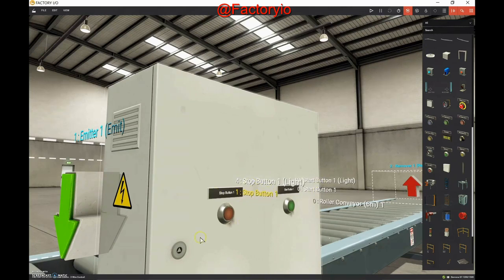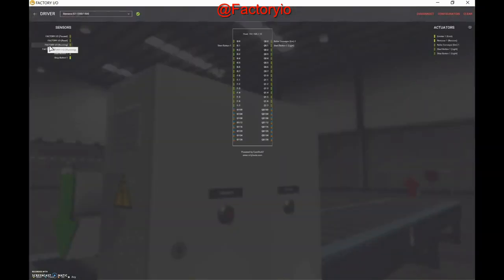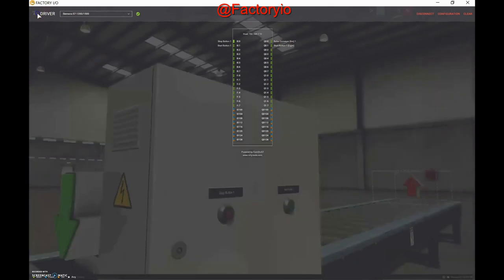Okay, now that we've added in this new input, we need to account for it on our I/O. So we're going to go to File, and Drivers again. That's why I put the start button at input 0.1, because I knew in this next video I was going to put the stop as input 0. So I am left clicking on here, dragging this over, hovering it until it sits on top of this unit, and dropping it in. Now I've got my stop and my start, and the same two outputs that are there. Okay, we'll go back to our animation.